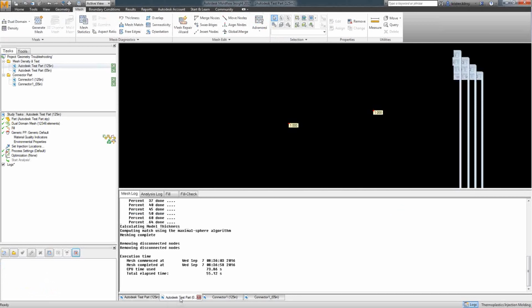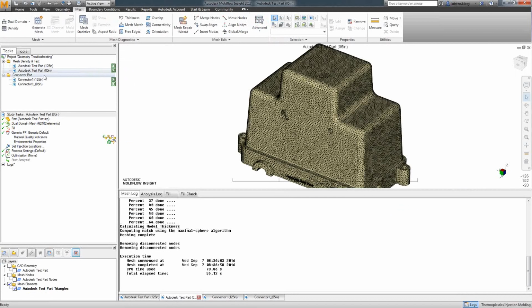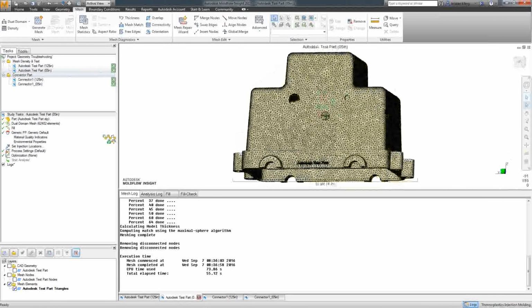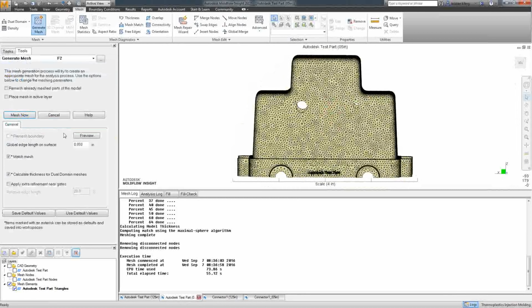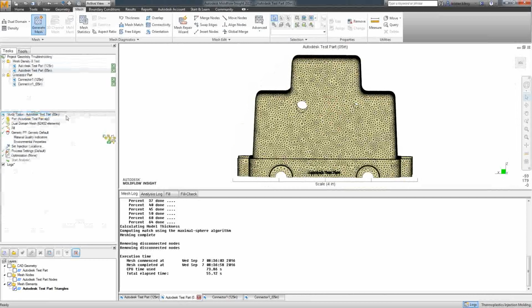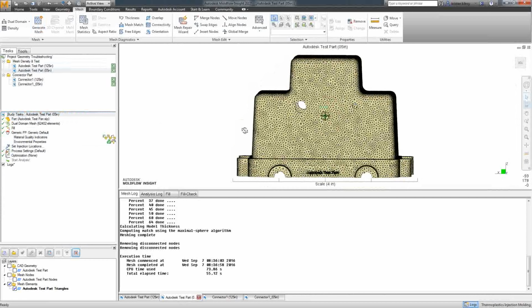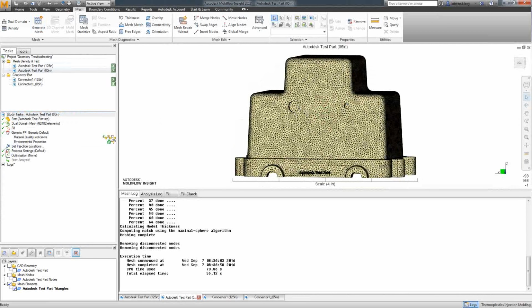But once you switch it over to a more refined mesh, about 50 thousandths of an inch, you can really see that round circle. And again, if you're working a lot with circles, the chord length feature can also help to really capture that roundness.